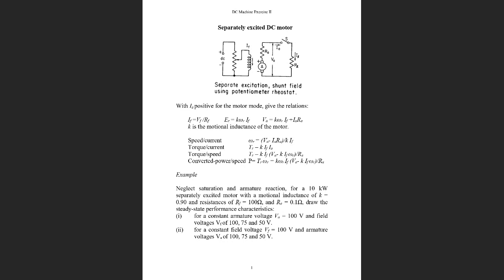By applying a current, we induce the voltage, and therefore induce torque and rotation. So the applied voltage is bigger than the voltage induced internally on the armature. We explained this in the lectures already. Those are the three basic equations representing the circuit.